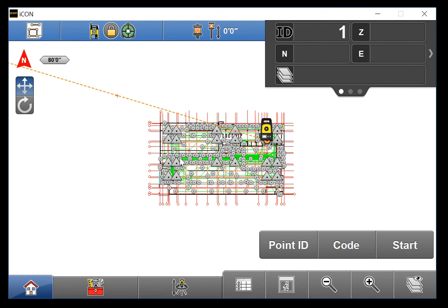If you do not see any points or lines on your map view to select, check that they are turned on through your Layer Manager. Refer to Video 15 for a refresher on the Layer Manager. If no CSV or DXF files appear in your Layer Manager, ensure that they have been properly loaded to the job associated with the floor you are working on, within the project you are working on, and that you are currently working in the correct project and job. You may visit Video 7 for a refresher on project setup and organization.